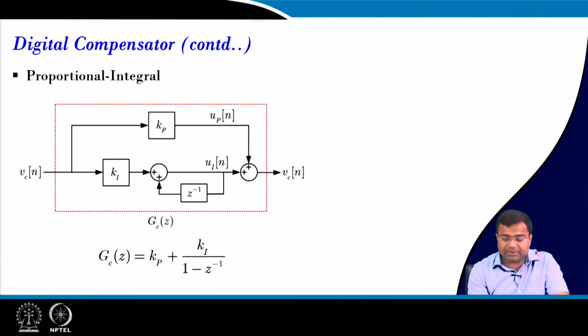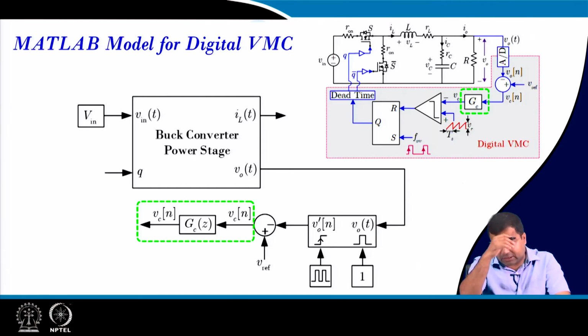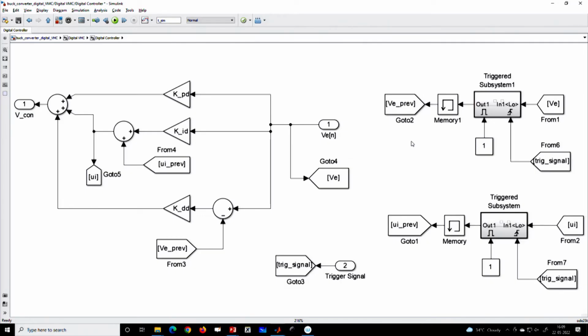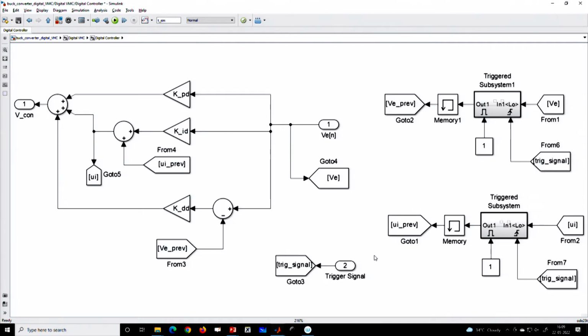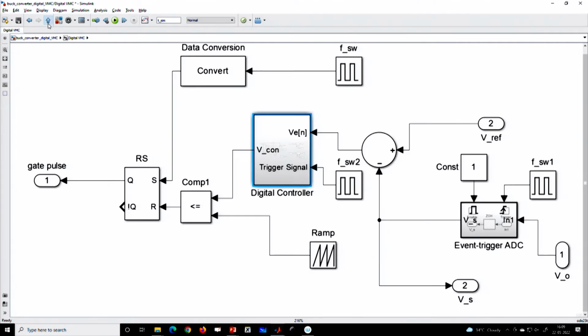Earlier one was the PI controller. So any controller that we can implement. Although this looks like a block, in MATLAB it is not a block, it is basically a difference equation if you go inside. So this is the whole realization. You can consider this part as your transfer function, and it is realized using a difference equation with a clock driven operation.